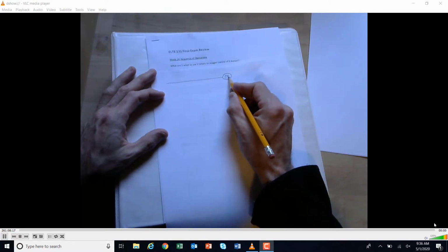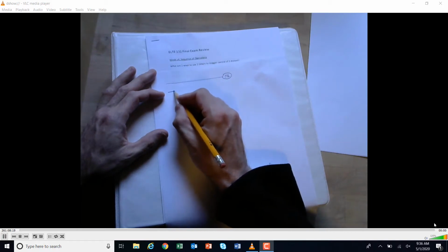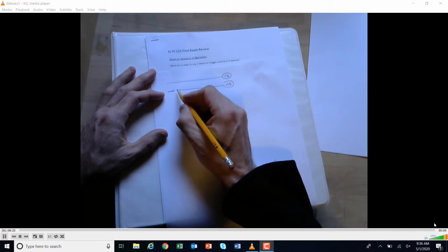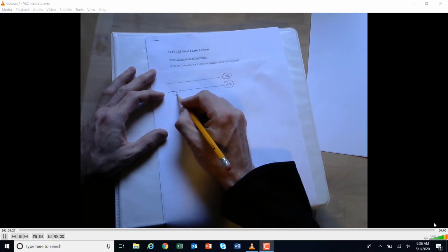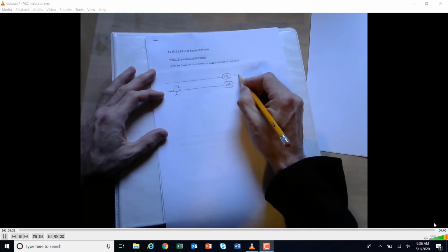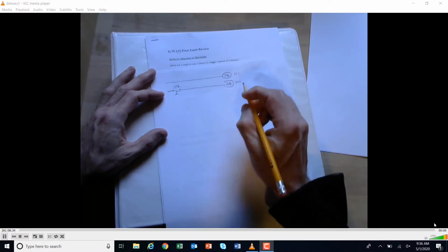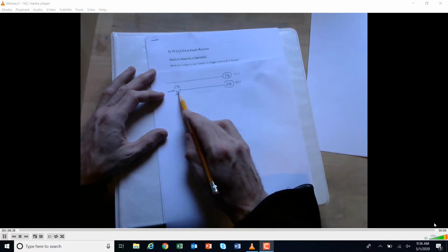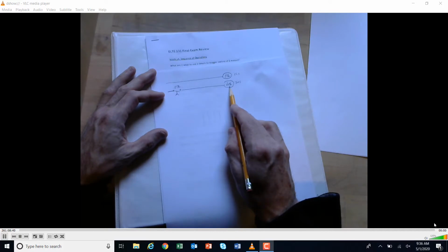And then this timer could have some contact that started the second timer, okay? So let's say this was normally open, timed closed, and that was the 1 TR. So if this was 15 seconds and this was 30 seconds, well, this timer would come on, and after 15 seconds this would close and the second timer would come on.